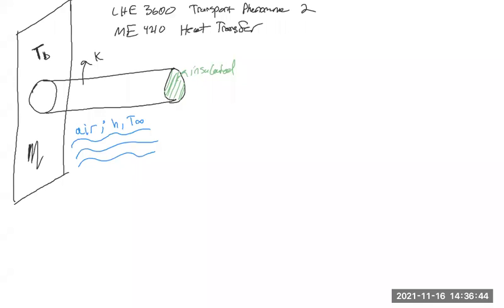When solving these kinds of problems, what you'd want to know is the thermal conductivity of the material. And usually there's convection going around a fin or extended surface, which is either heating up the fin or cooling it down. Usually you'll know the temperature of the surrounding air cooling down the fin, and the heat transfer coefficient. Once you have the differential equation, you'll want to solve it and apply boundary conditions. Typical boundary conditions are the temperature of the base itself, and if the fin has an exposed surface at the end, you could say that side is insulated, meaning there's no heat conduction once you travel down to the end of the fin.